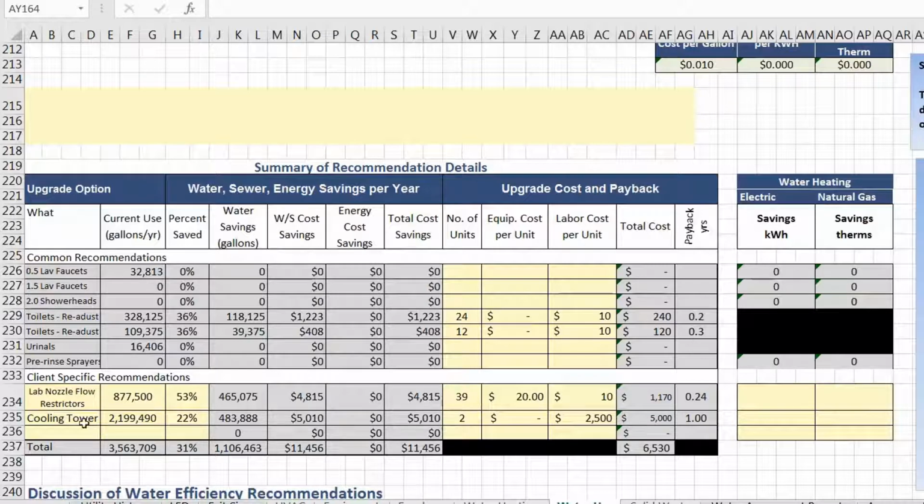This particular building had a major cooling tower management issue, where a lot of the cooling tower water was really almost going through in a once through fashion, and there weren't controls to recirculate that, and a conductivity controller to monitor and reduce the inflow of that.